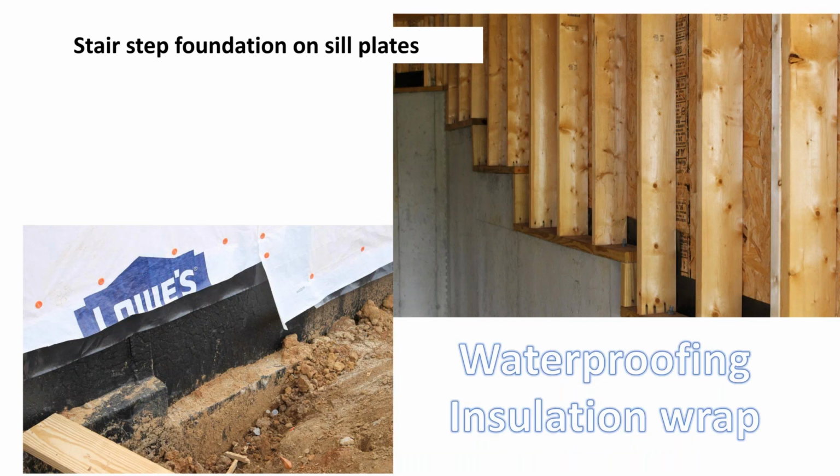There's a close-up of the stair-step foundation, and these are the sill plates. What's called a sill plate is what is between the stud wall and the foundation wall. The sill plate is what you will often see in a termite report. If they reflect that the termites have eaten the sill plate, that's what they mean. This plate right here has to be chinked out and replaced in the event it's been chewed up by termites.